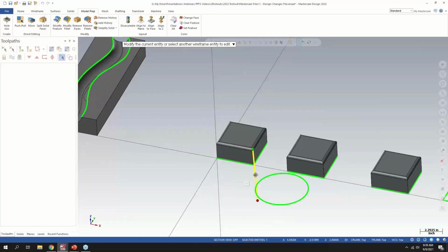So if it's a line, you'll get a midpoint to move it, or you can also switch here. There's a little button that pops up, kind of like the dynamic gnomon does, where I can switch between functions within this function. So instead of moving it, it's now set to copy, so I can do more of a transform command right in there as well.